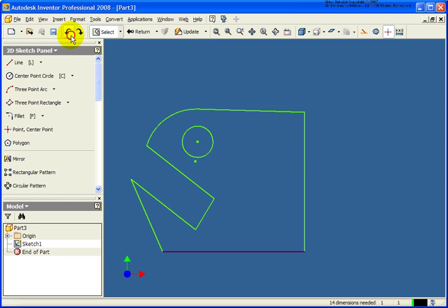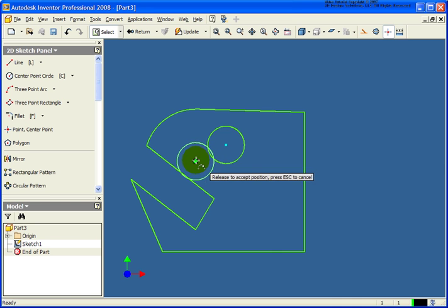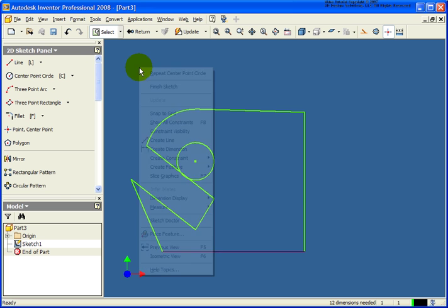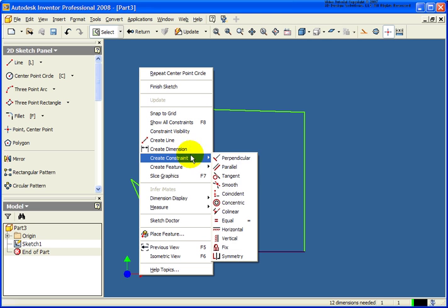Of course, in this case, when I was drawing that, I simply could have selected the center point of that arc for the center point of my circle. Or the other option to do that, let's say I do have a circle that's already drawn here. I can just press the escape key and just simply drag the two center points together. So those would now be concentric, or in this case it's a coincident constraint. In this case, the exact same result.